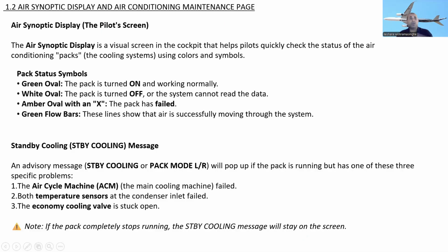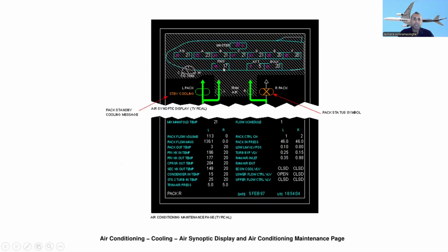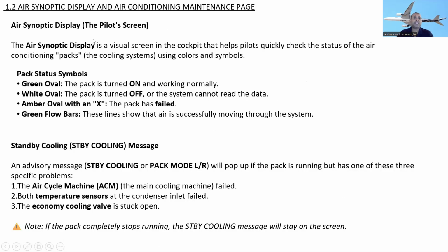All right. Now let's go to the 1.2 air synoptic display and air conditioning maintenance page. Yeah, this is the air synoptic display and air conditioning maintenance page. Okay, you can see this one. Let's learn about this. So, air synoptic display, the pilot screen.